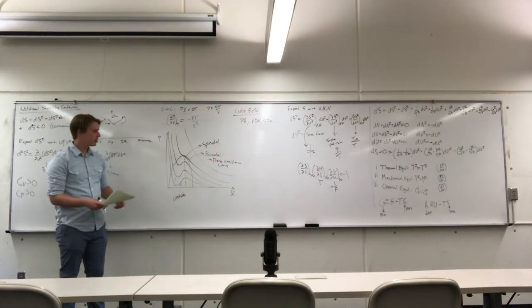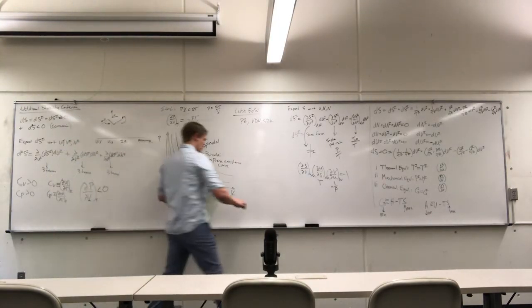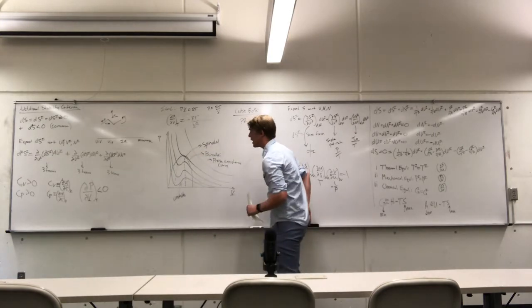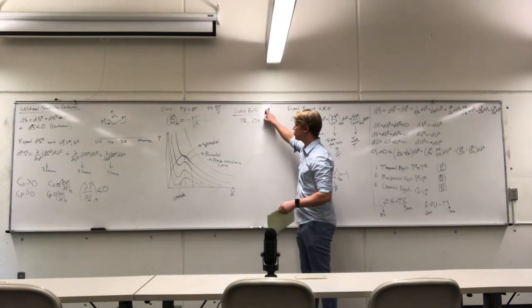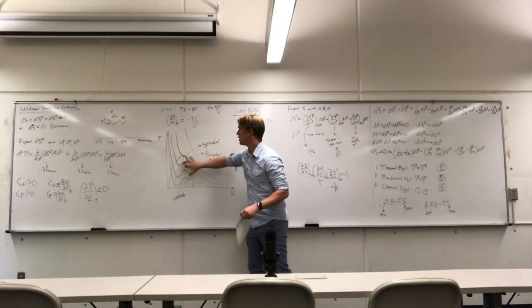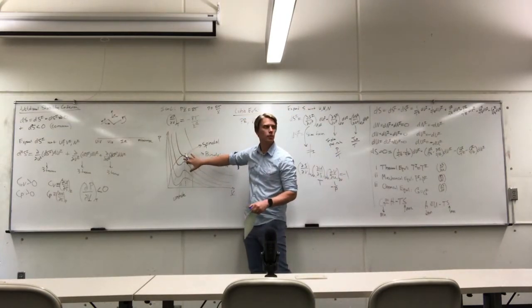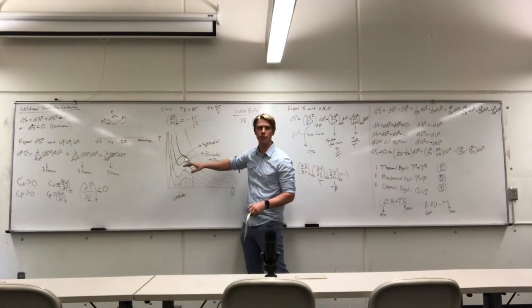So in a real system, the cubic equation of state just so happens to have a very useful functional form. It is, in fact, the simplest function that we can use to generate regions of unstable fluid and regions of pseudo-stable fluids.